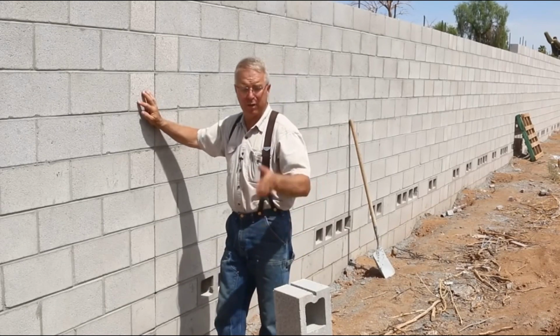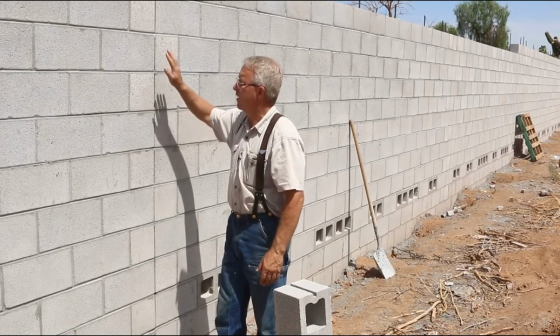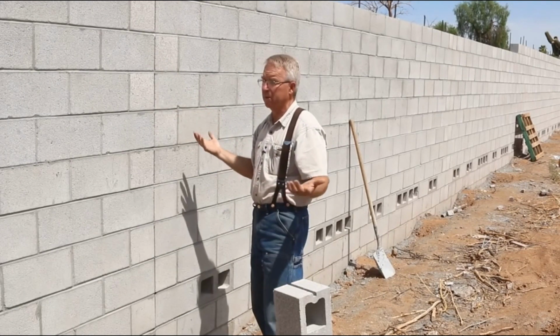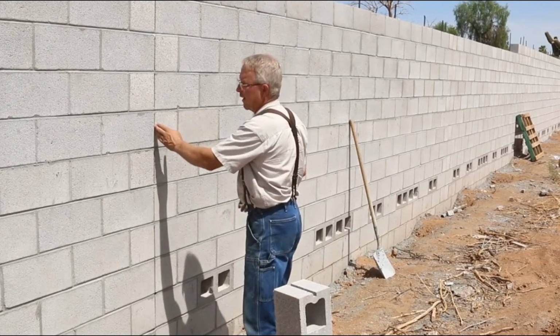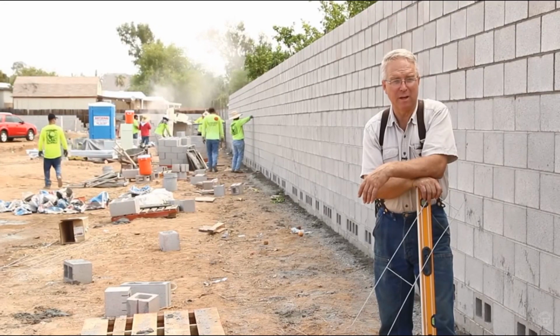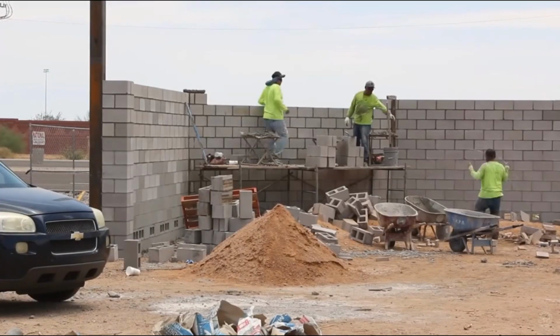It's just like control joints in a sidewalk or a driveway or a concrete retaining wall. This is to try to force any cracking that might happen because of soil movement or for whatever combination of reasons. It tries to isolate the crack at each location, and they're 20 feet apart. Masonry as a trade is a fascinating thing. It's been around a long, long time.